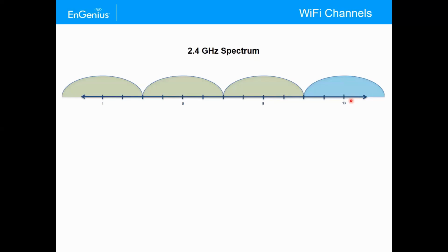Some other brands, however, let's say, for example, DJI, have drones running on Wi-Fi frequencies. If you buy an FCC drone, meaning bought from the US, it's hardware locked to only work with 11 channels. So basically, you cannot connect to channel 13. So in general, if the device is in the US, because they follow FCC standards, you can only play around with 11 channels on the 2.4 gigahertz spectrum. If a device is bought from Japan, you can actually use 1 to 14. For the rest of the world, Europe, Asia Pacific, we can use channels 1 to 13.